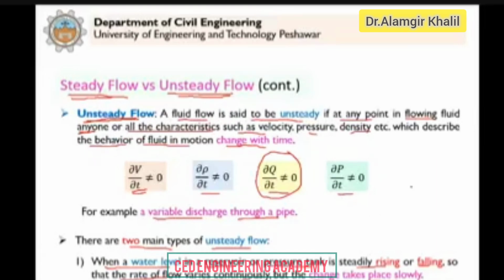So what is this problem? For example, what you studied in fluid mechanics, the orifices. Let's say we have a tank, and we have this orifice, and from here the water flows out. This water flowing out from the tank through an orifice is discharging under this head H. And you already studied orifices in detail. For example, the discharge for this orifice will be equal to cross-sectional area into square root of 2gh.